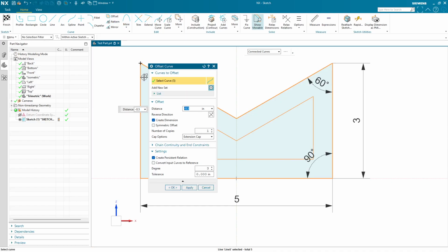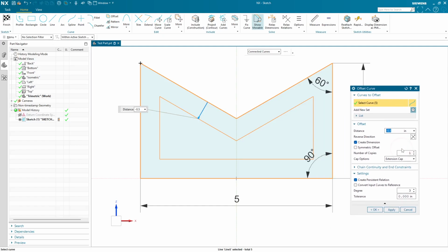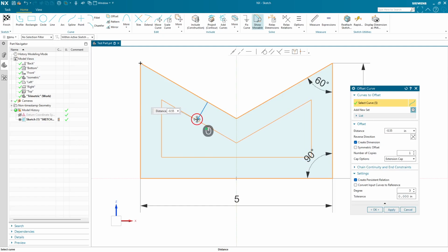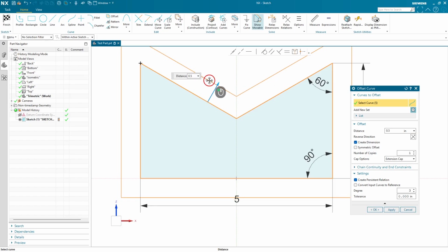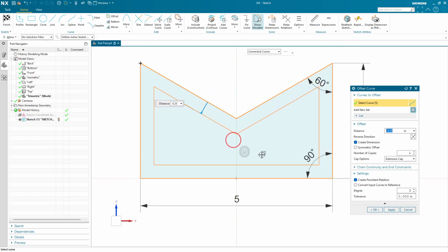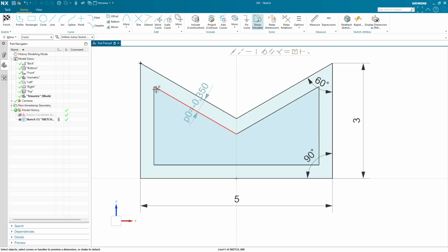Again, I hope some of these are self-explanatory. So it's a bigger, bulkier menu, but I can say minus 0.5 inches brings it in, or plus 0.5 inches brings it out. And then when I hit OK, we get a solid line. So if you need an offset, let's say we're trying to make just this shell-shaped thing, we don't want the inside, we'd probably want to come in and do something like this potentially. But explore these menus a little bit.